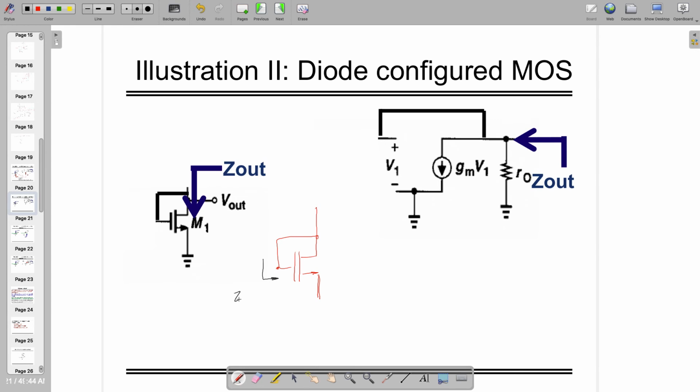So what is the gate impedance? Why RO? You look at that one more time, please. Yeah, so RO in shunt with 1 by GM. Very nice. So you can approximate this to 1 by GM. And there is no doubt that at drain side also I am going to see the same thing, right? It's shorted, so it's the same.